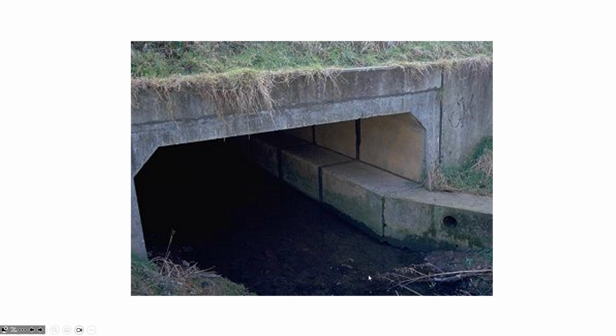Sometimes the culvert would have a natural channel underneath where they just build over it, but leave the original natural materials underneath. You can see that over time, depending on the flow conditions, the water can do quite a lot of damage to the bed, and there can also be scour and damage to the side of the culvert that affects the flow capacity.